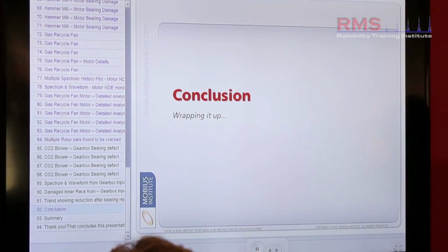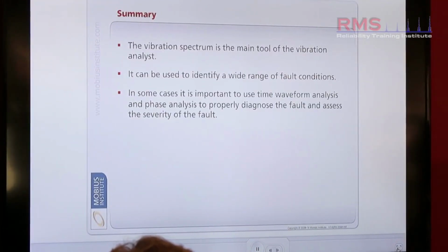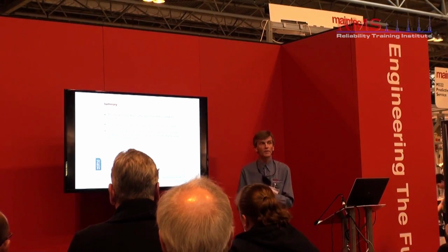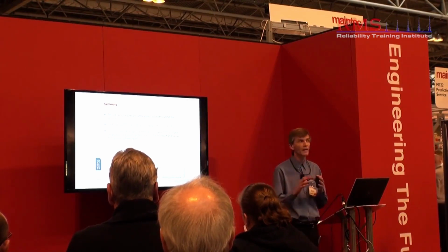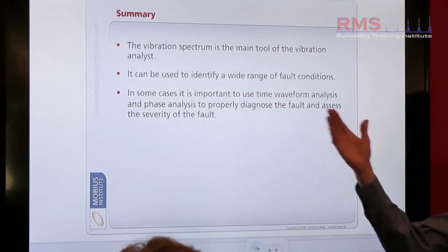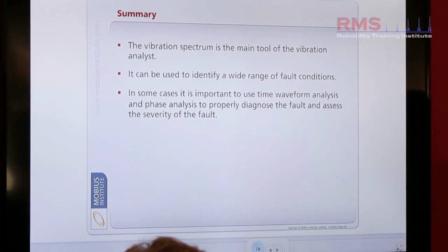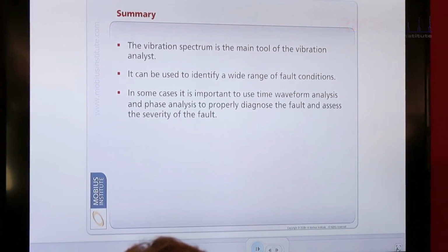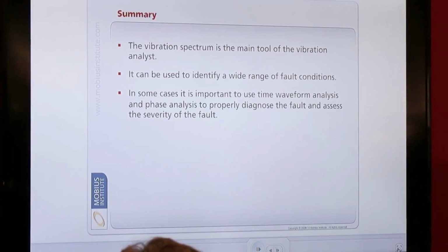So, in summary, vibration is a useful tool on generally rotating equipment. It's fair to say, supplemented maybe by high frequency methods. It can detect a wide variety of different defects on rotating plant, and understanding the actual signals, the heartbeat, is the key to understanding what's causing the problem, and then judgments can be made as to when you're going to do your corrective actions.